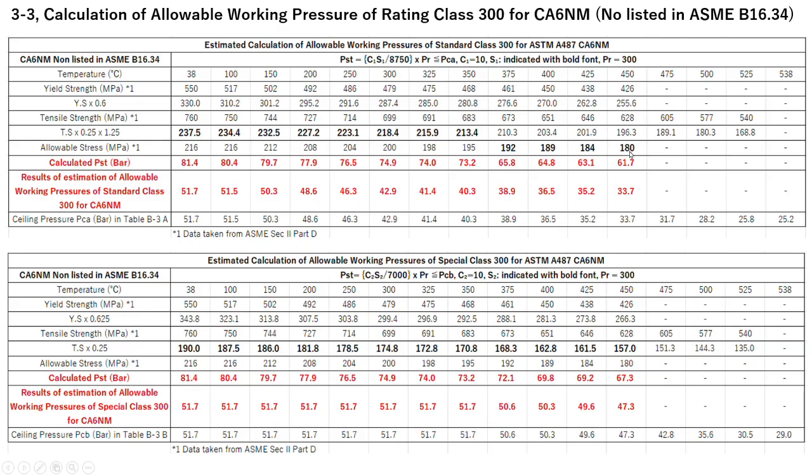In case of the bolt material also, assign the ASME Section 2 Part D specified temperature limit.